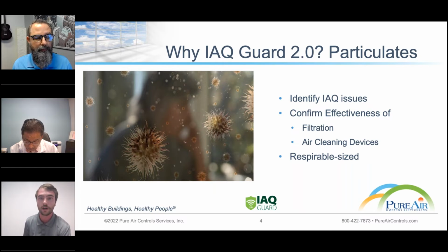Particulates are a wide range of aerosols that can affect occupants' health in different ways. We measure for 3 different sizes of particulates, everything from smoke particles in the PM 1.0 size all the way up to particles like pollen, human hair, dust, things like that, that all play into your indoor air quality and your occupants' health.